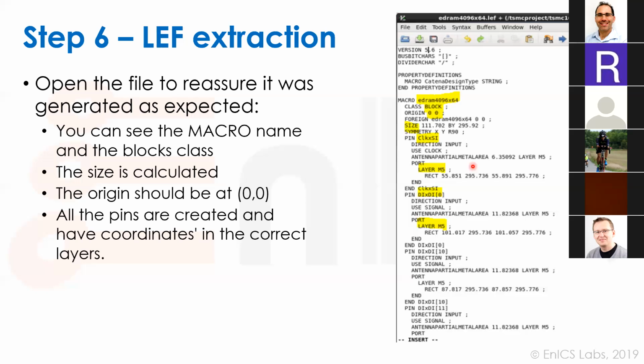It doesn't see anything beyond that, and it for sure sees what it should see, including the pins at the borders, the power layers showing the powers where they're supposed to connect, the whole pin, not just a part of the pin, but not showing power layers that are down below, having blockages at the layers that you don't want to route through your macro. These things are very important.